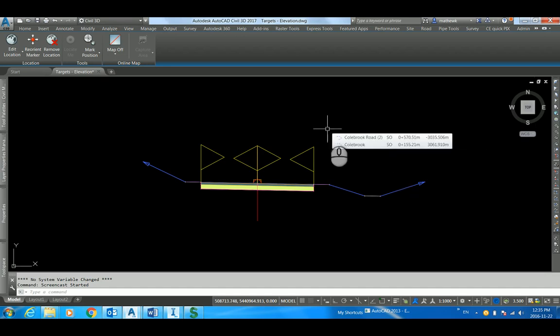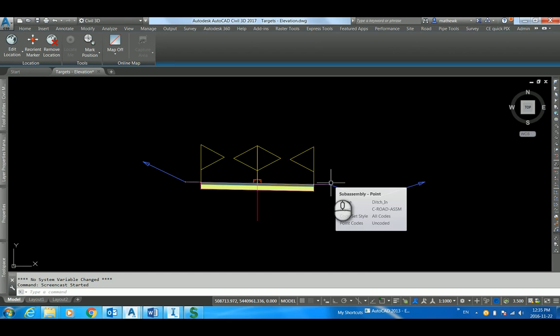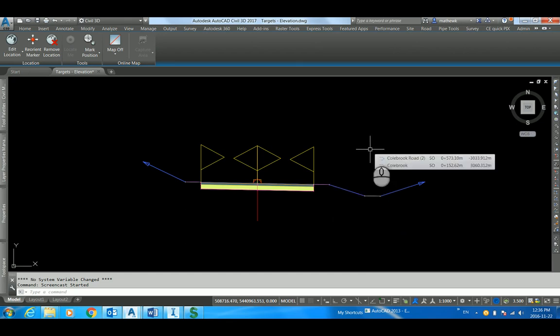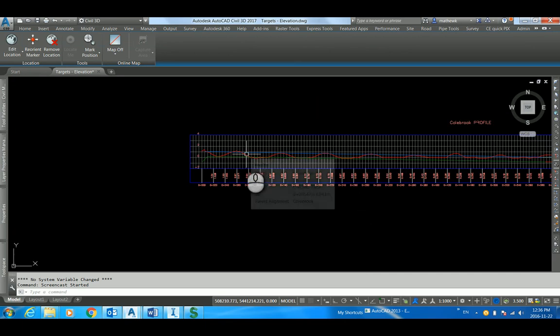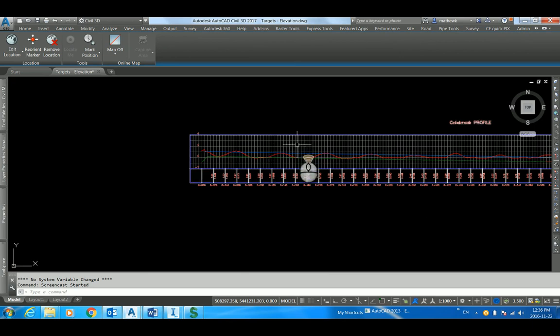In this case, our assembly contains a ditch created from such subassemblies as the generic links. In a general case, this ditch is 750 millimeters deep from the hinge point. And generally that's the ditch design that we're happy with. But in our case, the profile design dictates that in some cases the ditch must be deeper.